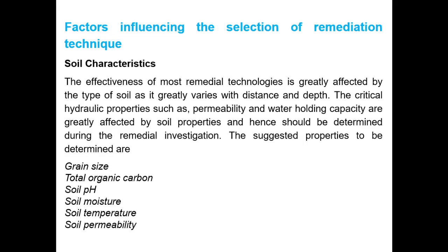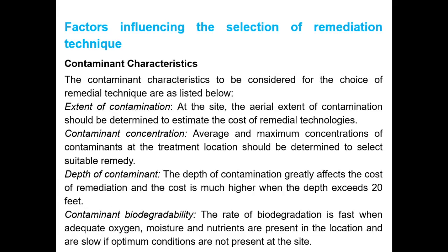Soil permeability greatly influences the efficiency of in situ treatment technologies. Low permeability reduces the capability of remedies like soil flushing, vapor extraction, and bioventing processes. Next one is contaminant characteristics.